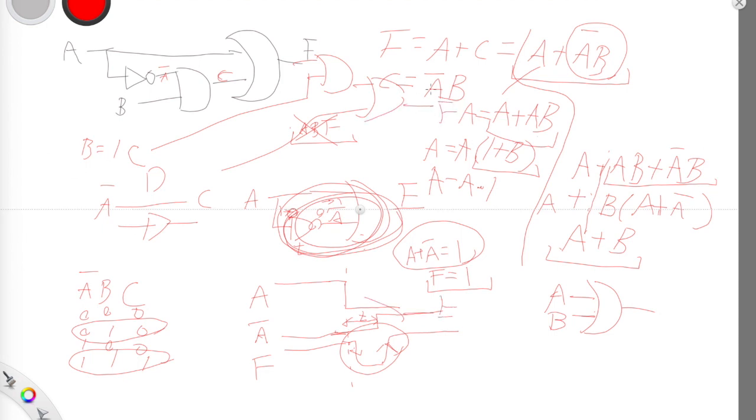Now, as you can see, if I added more gates, you cannot really use tables. I mean, you can, but it's going to take so much time. So the interviewer's intention is to not let you use a table. So you have to use a Boolean expression to reduce the logic. And you'll still get A plus A bar B plus C plus D.